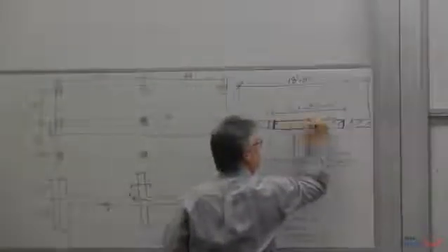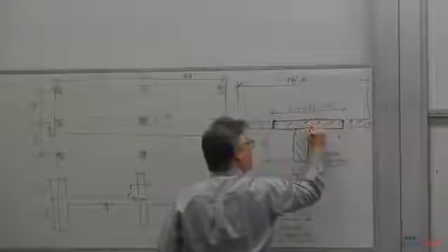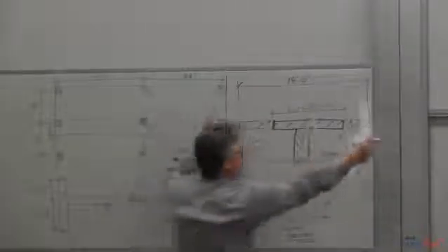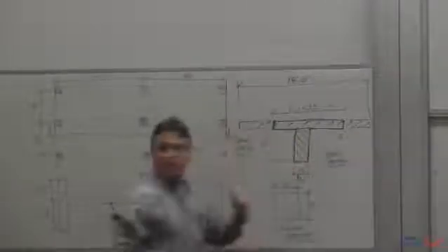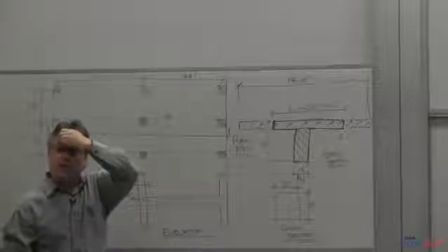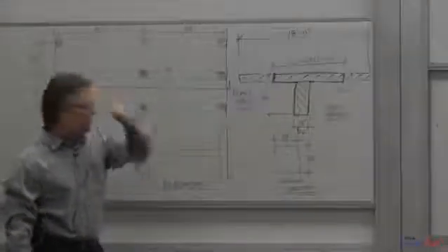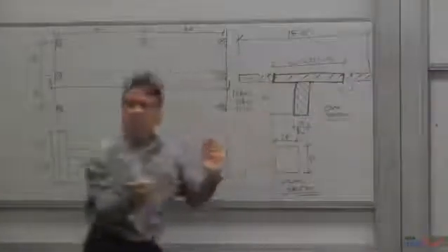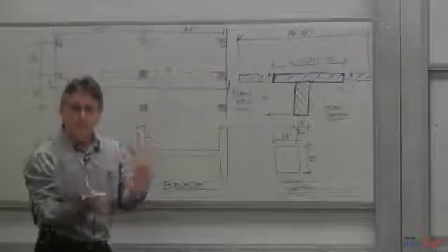Another thing that people get confused every year, this is the beam section for section properties. This is the full tributary area for the weight that beam has to support. Every year, I get a number of people who are confused between this distance, which is what the code limits you to in section properties.